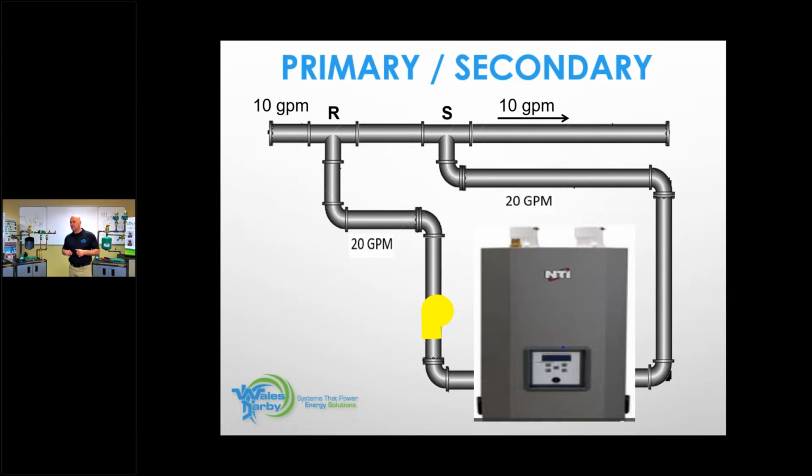All right, 2 for no flow. A majority are coming in at 10 GPM. 10 GPM. There's the answer. And it's reverse flow, right? Our boiler circulator is looking for 20 GPM. It's hungry. It wants to eat. Wants to run close to 200,000 BTU across this boiler. Our system right here is only taking 10 right now. So we would have 10 gallons of reverse flow to give that boiler its 20.